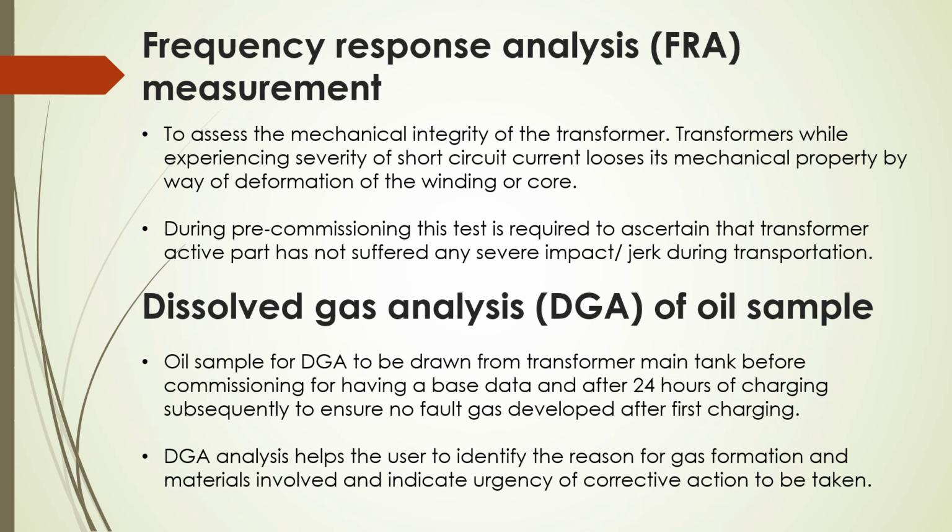Frequency response analysis measurement. To assess the mechanical integrity of transformers while experiencing severity of short circuit currents, it loses its mechanical property by way of deformation of windings or core. During pre-commissioning, this test is required to ascertain that the transformer active parts have not suffered any severe impact or jerk during transportation.